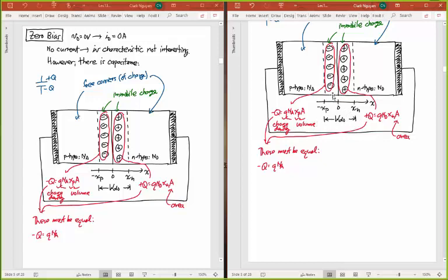Just from the geometry here, you can see that means the total distance. And so what I'm going to use is a parameter kappa, call it kappa p, multiply that by that total distance, where this represents just the depletion region on the p side. How much of the depletion region went into the p-type material.